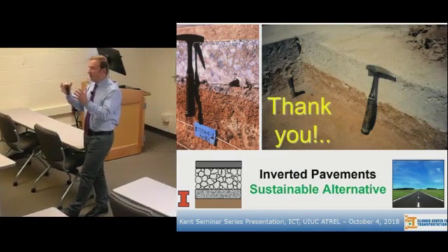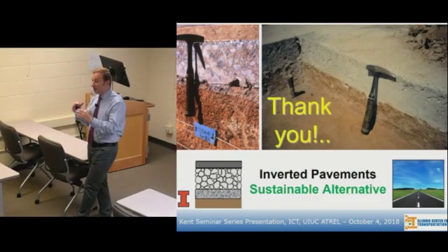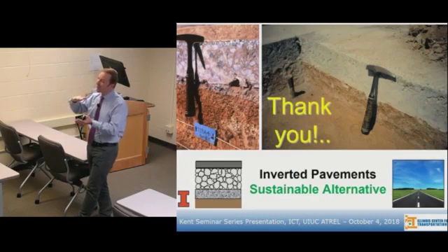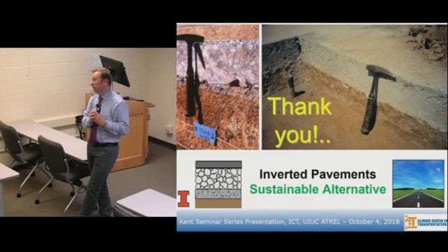And what they did, and I know this is a fact, is they started putting an interlayer of unbound aggregate on top. So they really pushed their heavy-duty cement stabilized base courses down to subbase, and they were able to prevent some of the reflective cracking in the asphalt by putting an interlayer of unbound aggregate under the asphalt in China. So again, with 3 to 5% cement, the cracking, if you ever get cracking in cold northern climates, is not going to reflect to the asphalt with the 6-inch aggregate base under the asphalt first. That's my opinion.